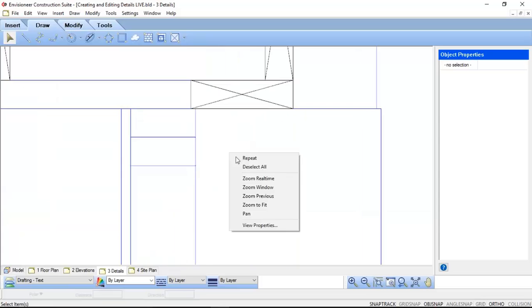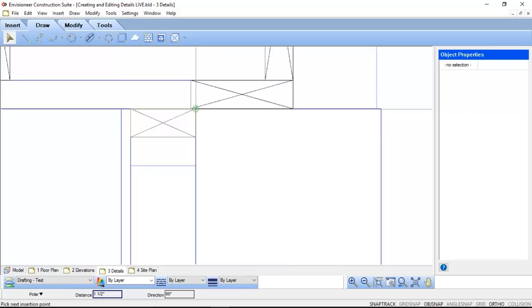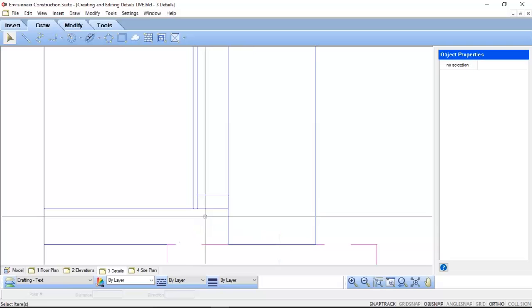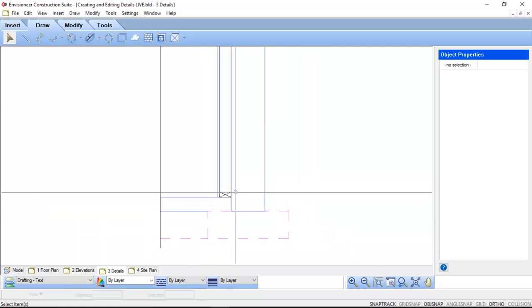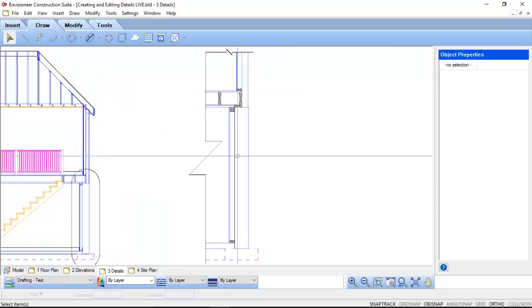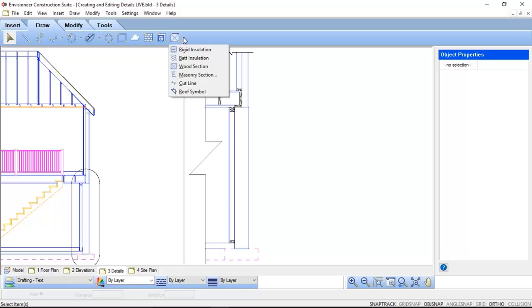We've got another couple of top plates here in this interior 2x4 stud wall inside of our foundation wall, so I'll add my wood section marks to those. And I've got one last one, this sill plate on the bottom sitting on the basement slab down here. So I've got my section lines in, I've got my wood section marks. I'm going to move on and add some other details under this detail button.